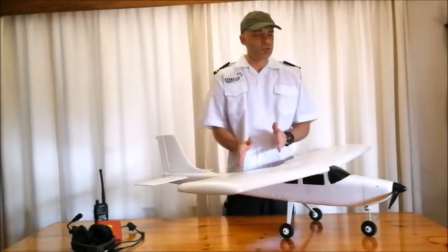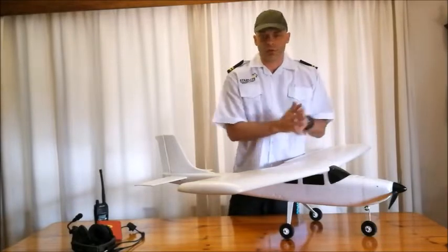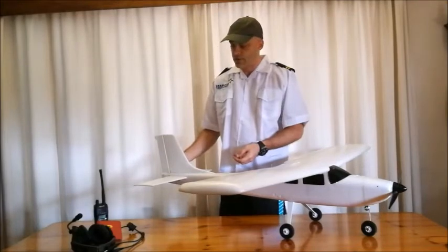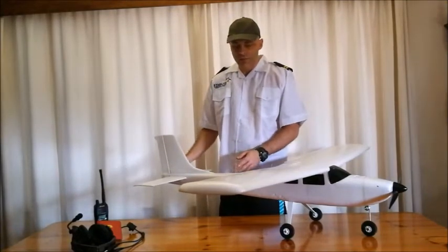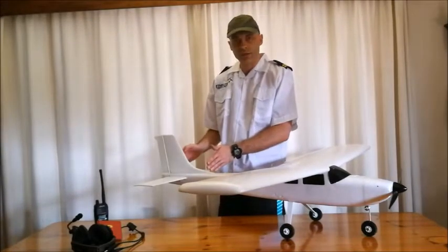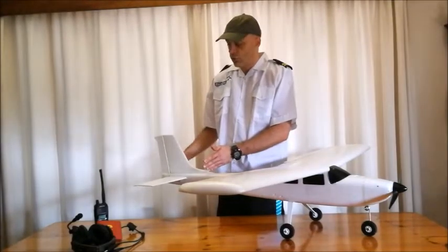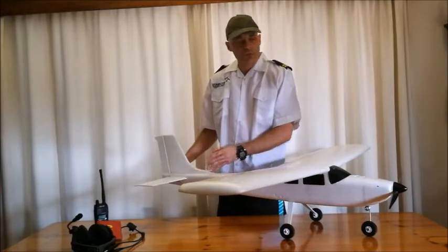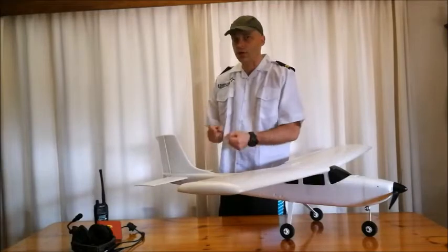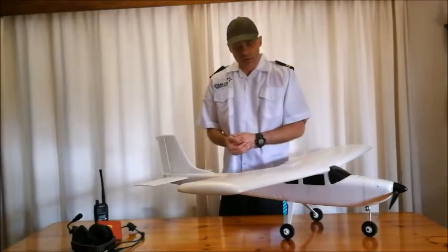And so you generally want to have the payload, or most of the weight, as much to the front as possible. The reason is that if you've got a control surface like your elevator that has to move upwards and downwards, and the center of gravity was towards the back, the arm length would be so short, and therefore the moment would be so short, that the amount of force the pilot has to put on the control stick to move these elevators up and down would be a lot, and it would be very difficult to make the aircraft pitch upwards and downwards.